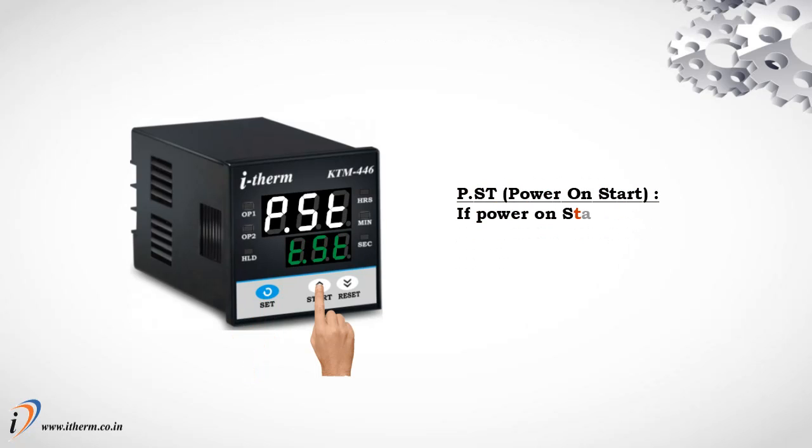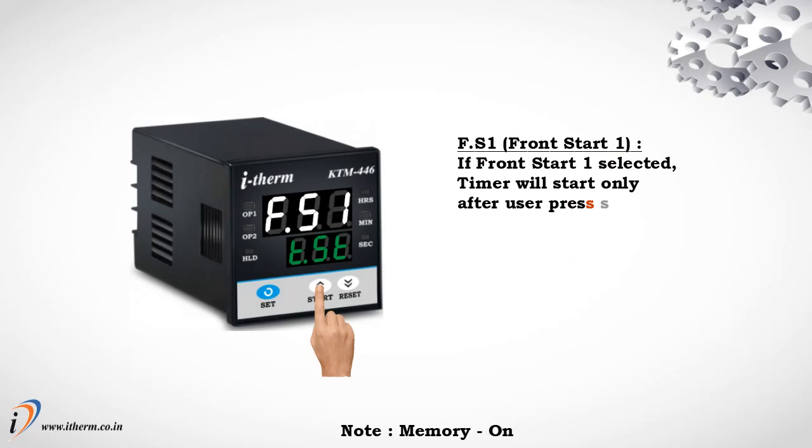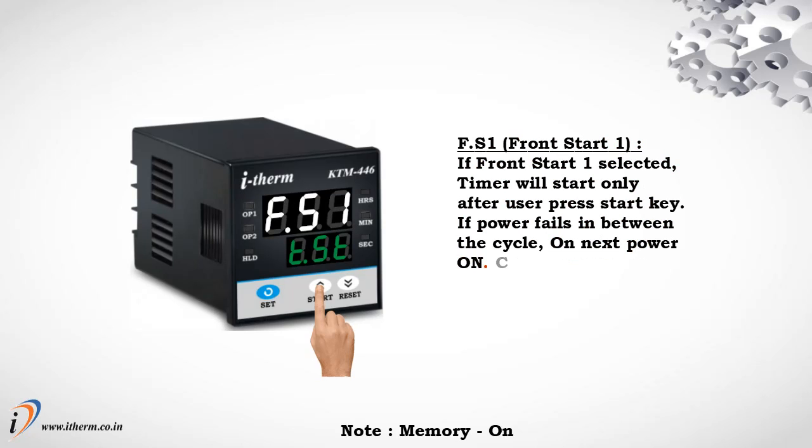Power on start. If power on start is selected, then the timer will count from power on. Front start 1. If front start 1 is selected, the timer will start only after the user presses the start key. If power fails in between the cycle, on next power on, the cycle will resume. No need to apply the start command.